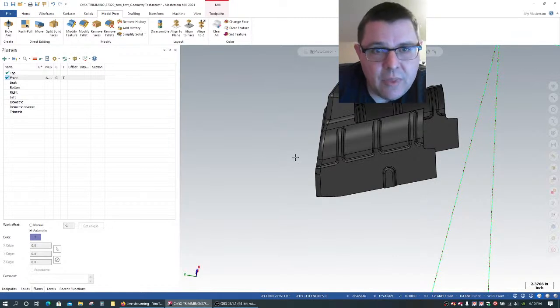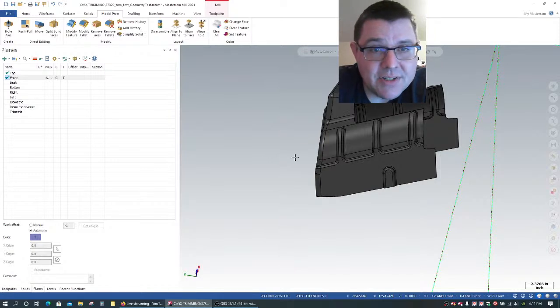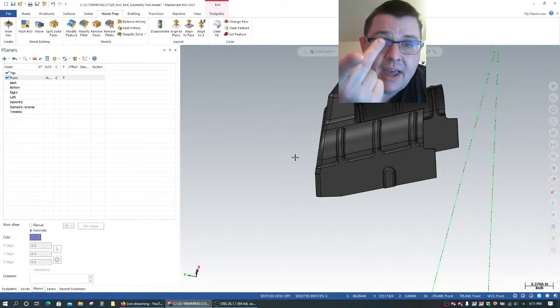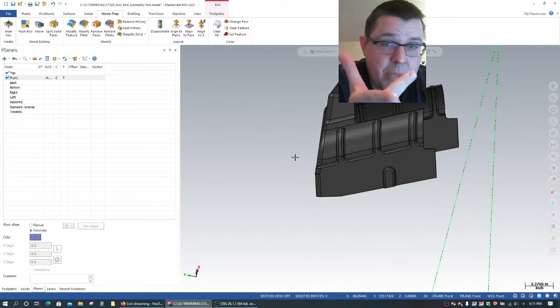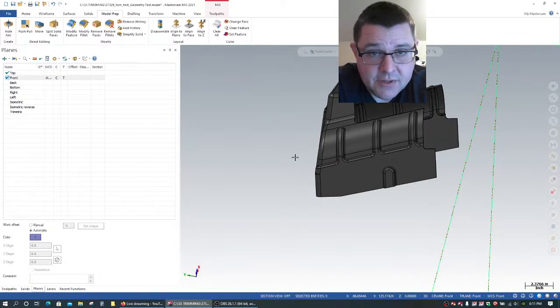And we do that internally, mathematically, with a matrix. So a matrix is, in terms of creating a coordinate system, 9 variables. There's 3 variables for the X vector, 3 variables for the Y vector, 3 variables for the Z vector. So by using these 9 coordinate positions, pure mathematics, there's nothing physical about it until we get out to the machine. But using pure mathematics, we can define a coordinate system in 3D space. And so that's what we do. We define what's called a tool plane matrix.